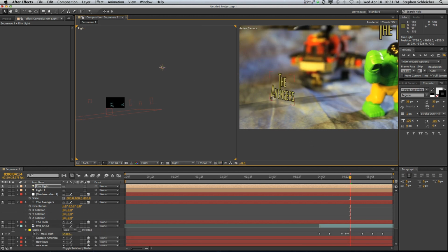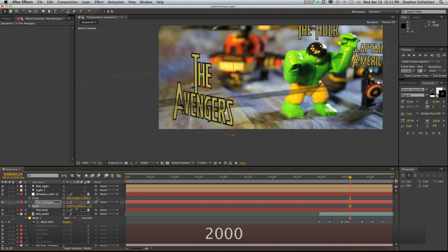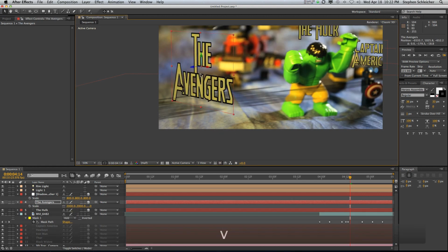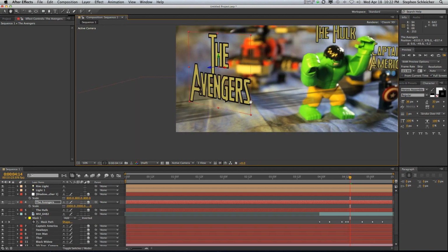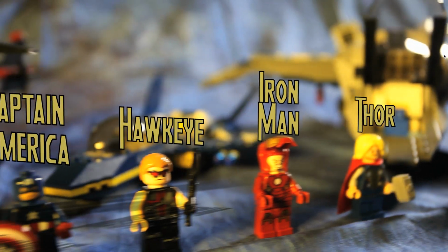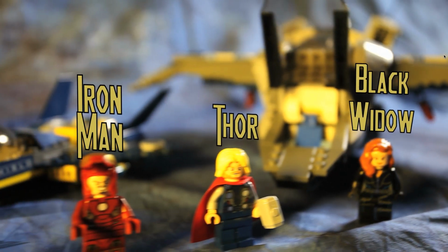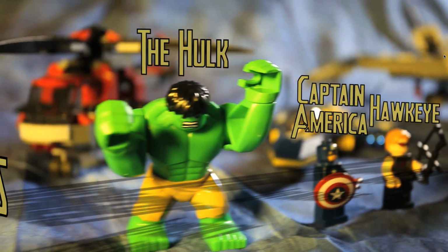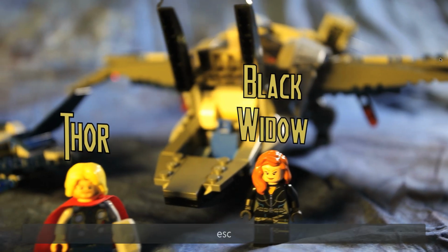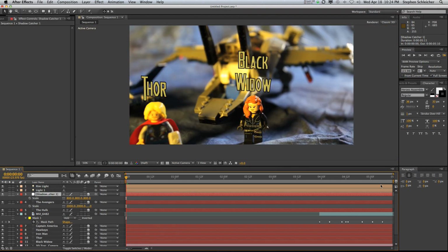So you can see our shadow catcher is now casting 2 shadows into this scene. And if we look at the overall, and there we go, a look at all of our elements. Obviously, there's a couple of things we have some issues with, the shadows being cast from the shadow catcher. The easy fix for that is to go in and change the size of the shadow catcher.